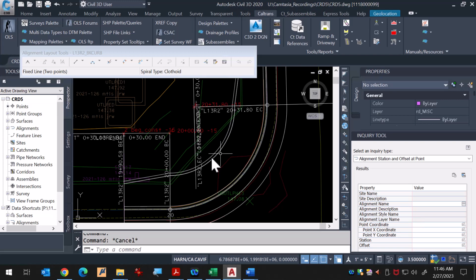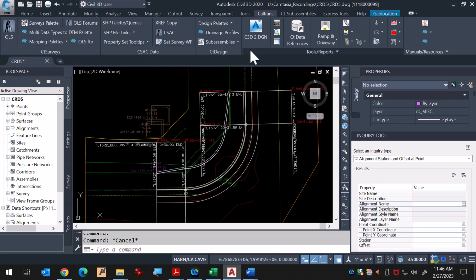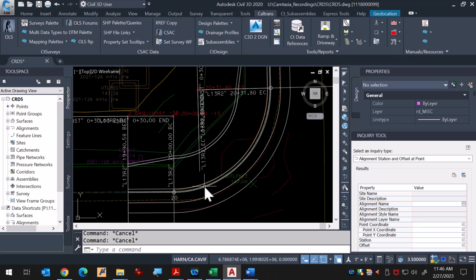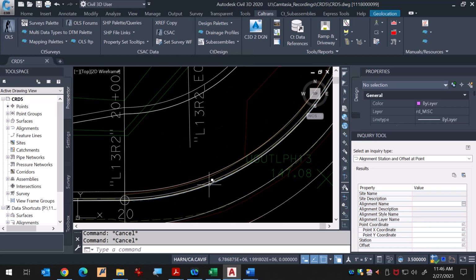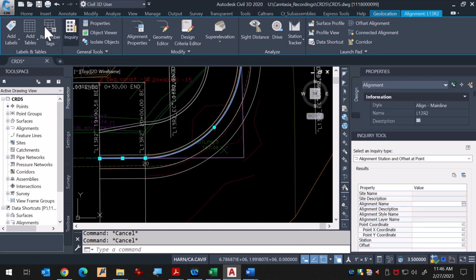The one other line that I'm going to put in right now, I'm going to attempt to put in the landing lines for our blended transition. So I'm going to try to go with a 20-foot entrance area at the flow line and see how that works with our ramps and things. So I'm going to try. These are just temporary or tentative lines. Remember, design is an iterative process. So I'm going to try this one at 20 plus 05. So I'm going to hit the flow line, and I'm going to create 2 points outside that so we can get our cross-section line at that point.